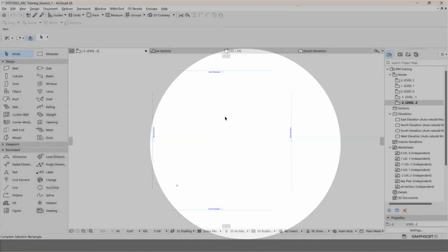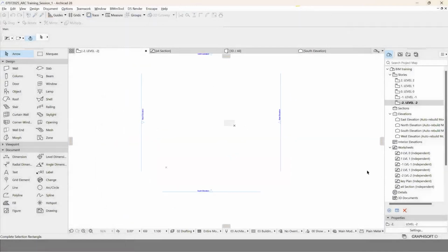To start with, we need to bring the reference here. You can also copy and paste it and then work on it. But like I mentioned, we have something called the trace tool that is going to make our life easier by focusing on specific elements. Otherwise, if you put it into the same space and click on the element, you might get distracted or the reference gets moved, and it might cause some issues in the modeling.